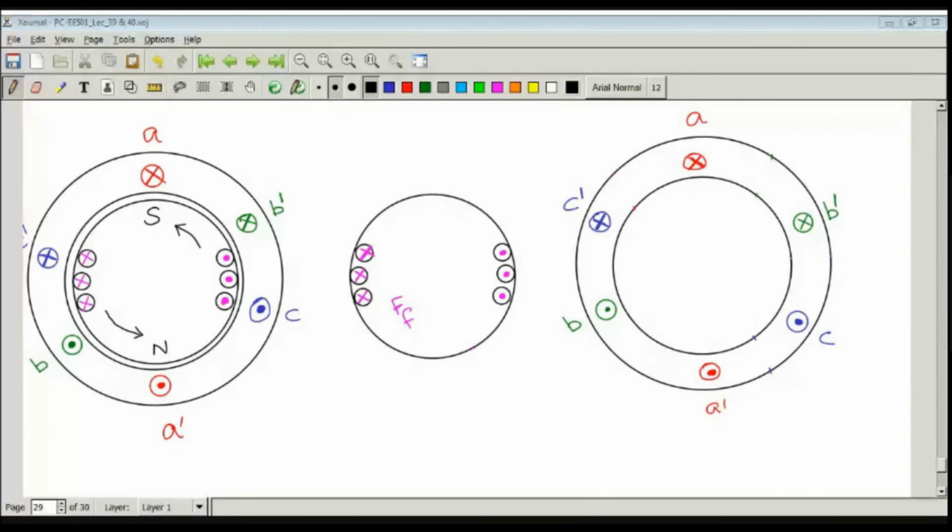In this lecture, we will study the effect of armature reaction in a synchronous generator if the armature current is at unity power factor. Unity power factor means voltage and current will be in the same phase. If you recall, in our earlier class we saw the effect of armature flux on field flux when the load connected to the armature winding was a 90-degree lagging power factor load. So we will now explore it for a unity power factor load.